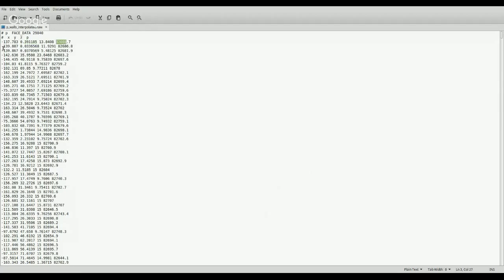So this way, you are able to apply a pressure and interpolate it on your load file that you will have to input to your stress analysis software. This way, you can take into account the output of CFD simulation to associate this analysis with the common stress analysis on your buildings.